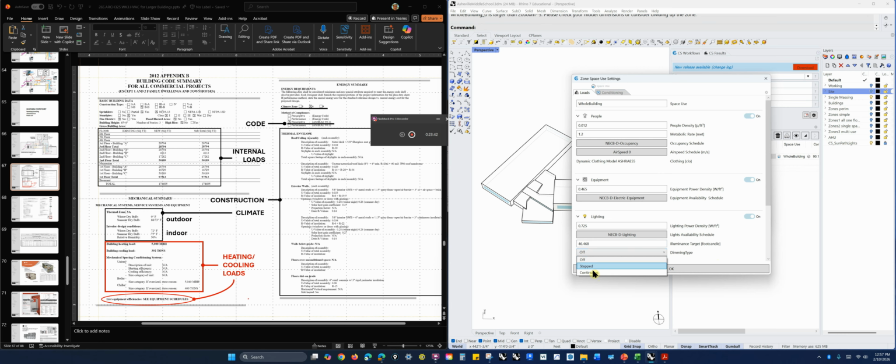And so if I turned on the dimming, let's say if we had a big south-facing room, and whenever we met this... The reason why it's 46.468 is because that's a conversion from a metric standard. This is in foot candles, so it's a conversion from lux.